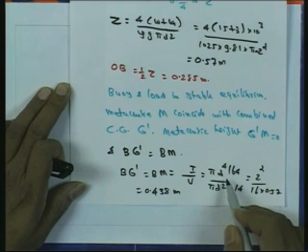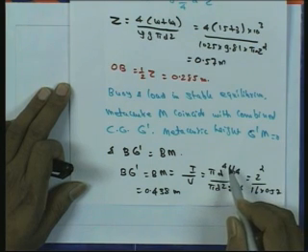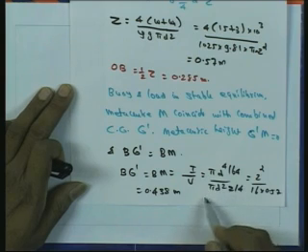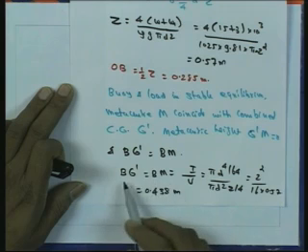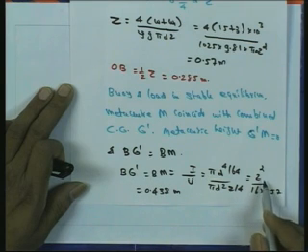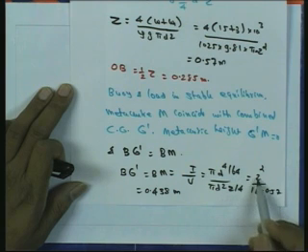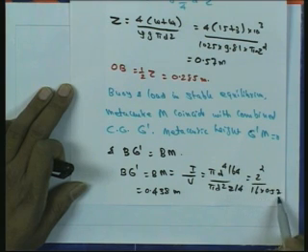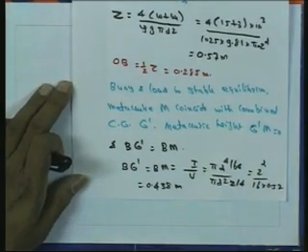Here I is equal to pi d to the power 4 divided by 64, and the volume of displaced liquid is pi d square Z by 4. So finally, we get BG dash is equal to BM is equal to d square divided by 16 Z. d is 2, so 2 square divided by 16 into 0.57, which is the Z we determined. So finally, we get BG dash is equal to BM is equal to 0.438 meter.